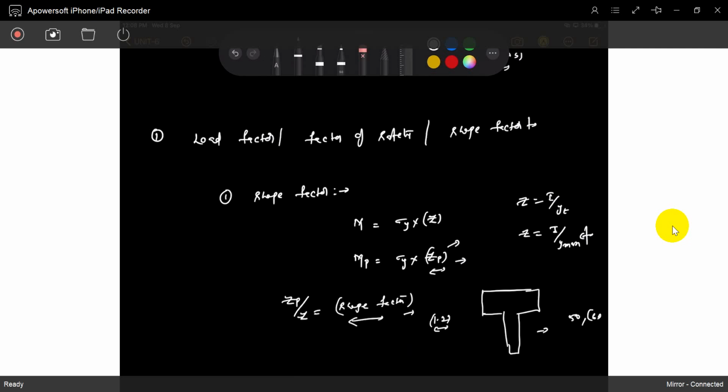It's 1.2, so 20% compared with the elastic analysis is already stored in the system. You can say how much energy is stored beyond the yield point. That is the purpose of the shape factor.